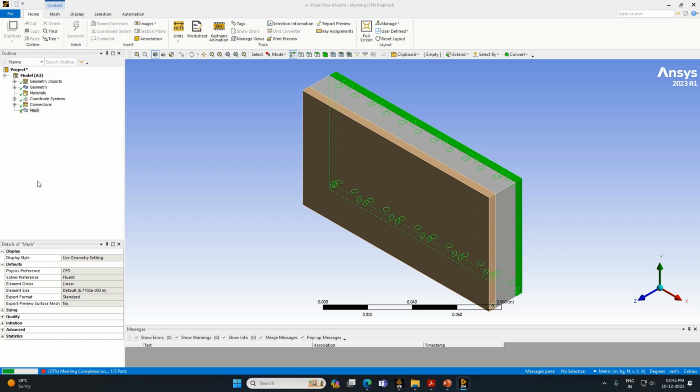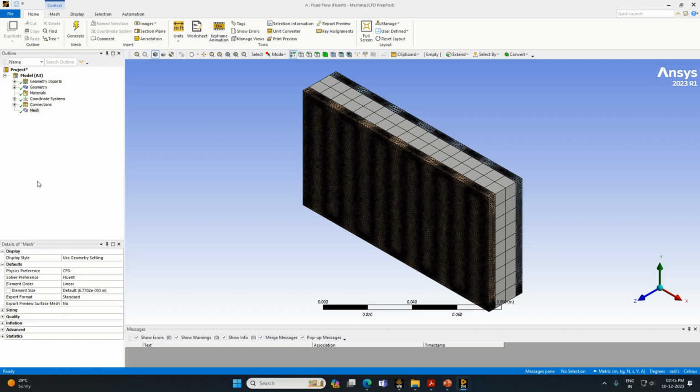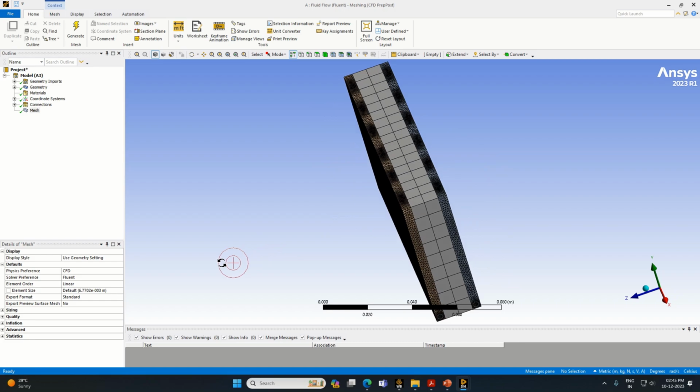For the understanding of your computer, the computer will generate the mesh. We'll make it somewhat fine so that things will be proper for us during the simulation. So we'll definitely change the default mesh size. The default mesh size is just for your understanding of how it comes out, and accordingly changes can be made on it. Based upon the nodes and elements, the computer may generate the default meshing over here. So it has been generated.